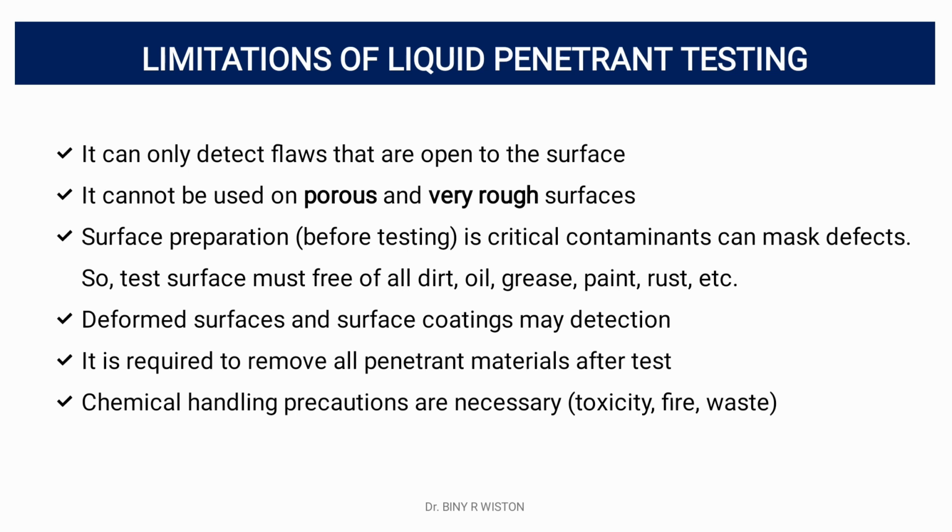Skill and training requirements. While the process is straightforward, accurate interpretation of results requires skilled technicians. Proper training and certification are necessary to minimize the risk of misinterpretation. Some penetrants and developers may contain hazardous materials which must be handled with precautions and with necessary handling, storage, and disposal practices.